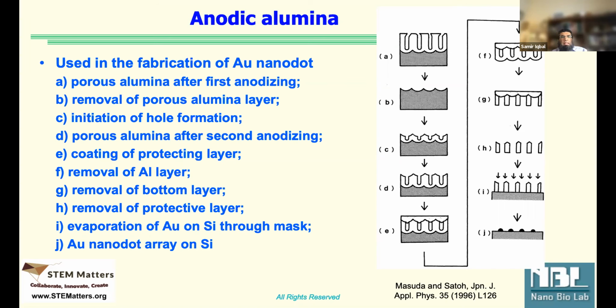So we make porous alumina with anodization, with that electrolysis process. You remove the alumina, you can etch it, and you get the surface at the bottom, which has a very well-defined structure. You grow it again with a second anodization, and ultimately you deposit metal. In this case, we are doing gold evaporation using that alumina as a mask and getting those layers.